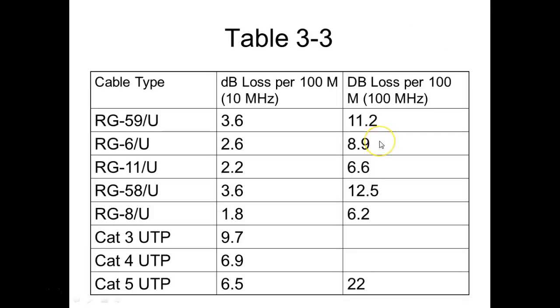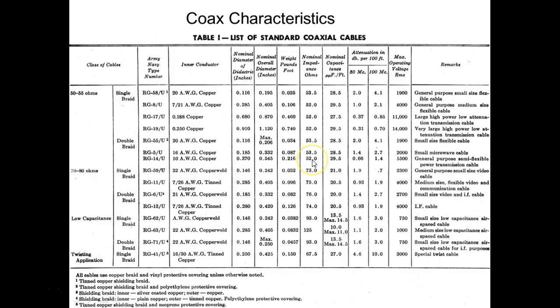The next, and these are different ones, and of course we looked at this, and these are what it's rated at in the different cables. What this next chart is, and I'll try to put this chart by itself, is it gives you the different diameters and everything of the cables. And what's nice about this, it gives you the gauge and the diameter of the cables. What we have here is RG58U. We call it RG58, but all of them got the /U on there, and exactly what that stands for, I've looked it up before, but I'll do that with this.